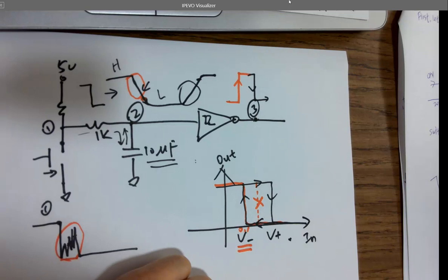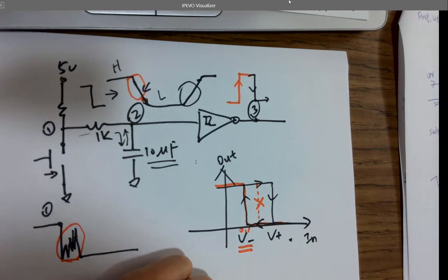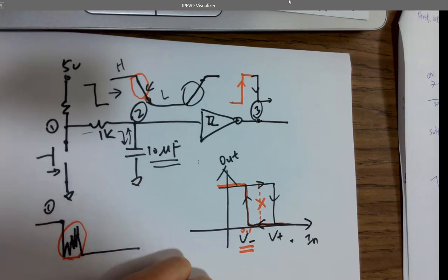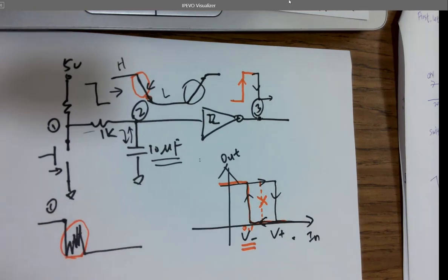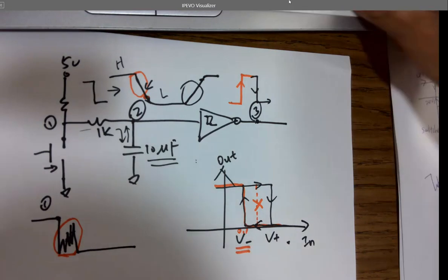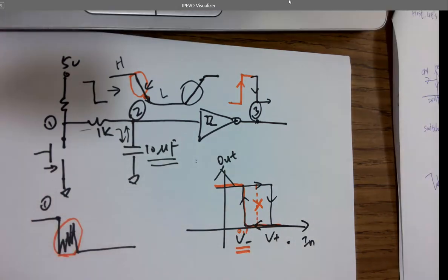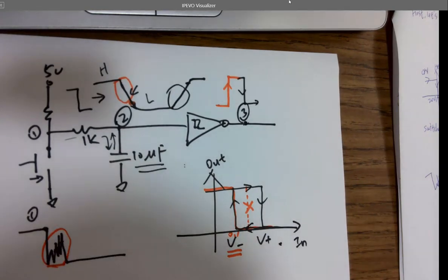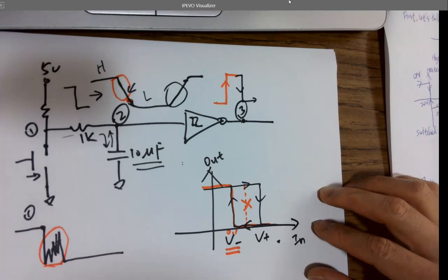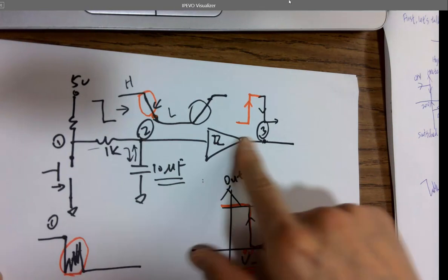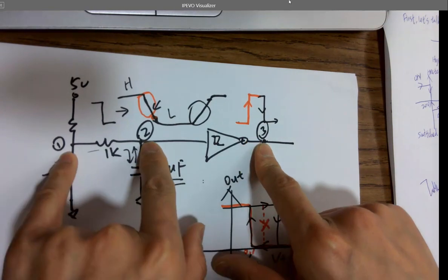This could be very useful for the FPGA project later in the semester. So we're going to build exactly the same circuit in the lab as part of the tutorial tasks. I think that's task 2. We're doing that in lab today. Yeah, no, anytime this week. It's just homework, yeah. So build this circuit on the breadboard and probe 1, 2, 3, and show it on the oscilloscope.